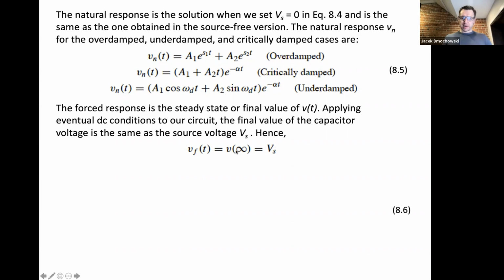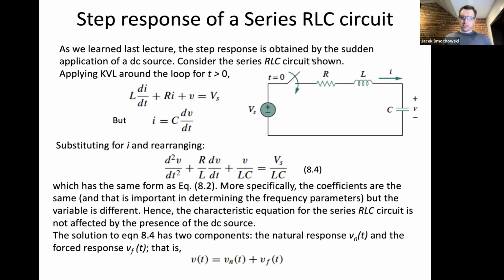definition equal to the capacitor voltage at time equals infinity, which is equal to the battery voltage. And let's look at why. So in this picture, imagine that the capacitor is an open circuit and that the inductor is a short circuit. Then essentially, all we have in this picture, try to draw this, is at time equals infinity, we have our battery, our resistor, our short, and our open.